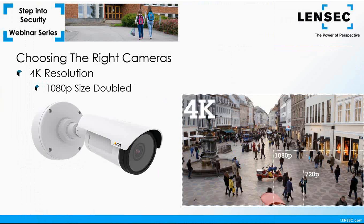4K cameras allow for increased detail and coverage area. The potential here means you have the chance to reduce the number of cameras needed to adequately cover an area. That equals lower system and installation costs, but it's not a magic bullet either. On the negative side, you'll have increased bandwidth and storage needs. Your load on the server and the client will be increased as well. In addition, you may have reduced performance in low light, depending on the camera that you choose. And your frame rates and video streams could be affected due to the higher resolution.